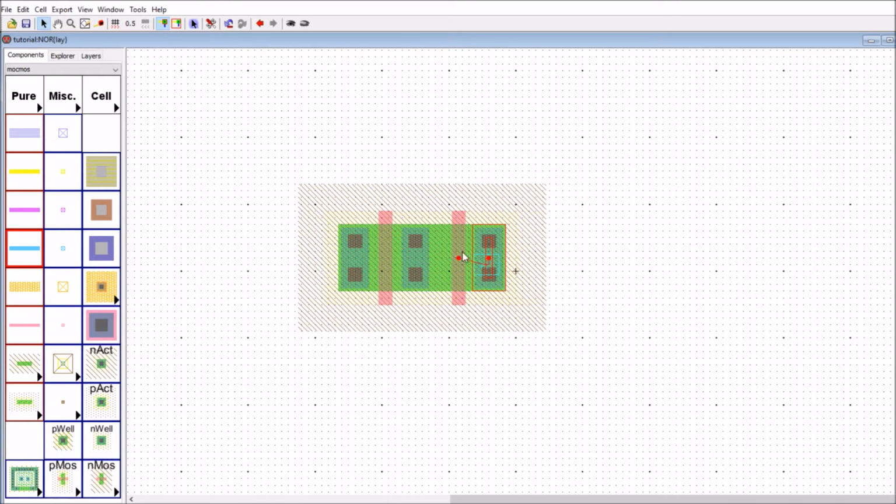Okay, just here, and we'll make it just so they're the same width here. Okay, so that's us created our two parallel NMOS devices. We're going to have a source here, we're going to have a drain, and we're going to have the other source. Now these two sources are going to get connected together and go to ground, and this drain here is going to head up and it's going to go to the output and also up to the PMOS devices.